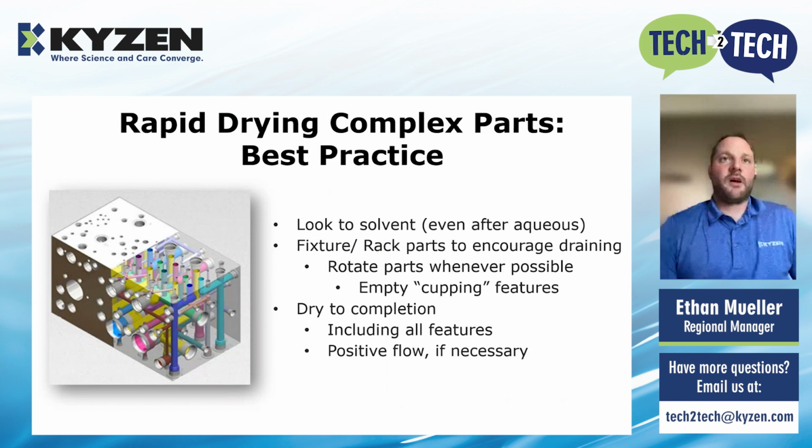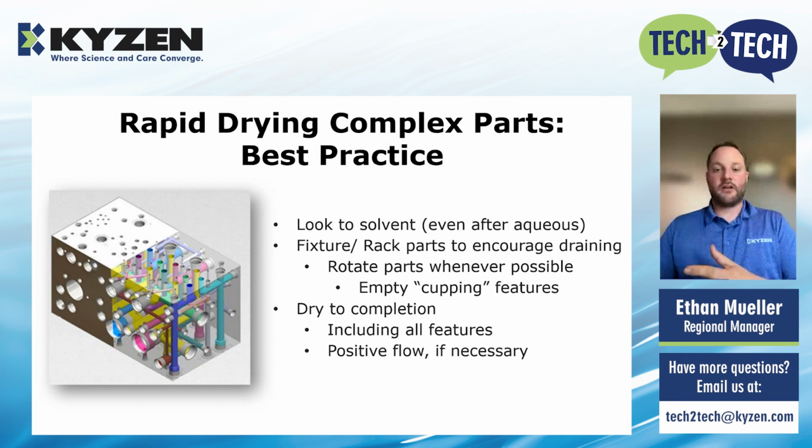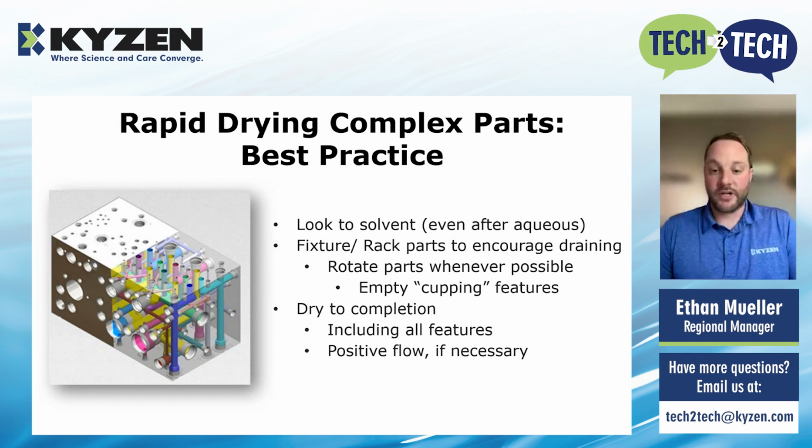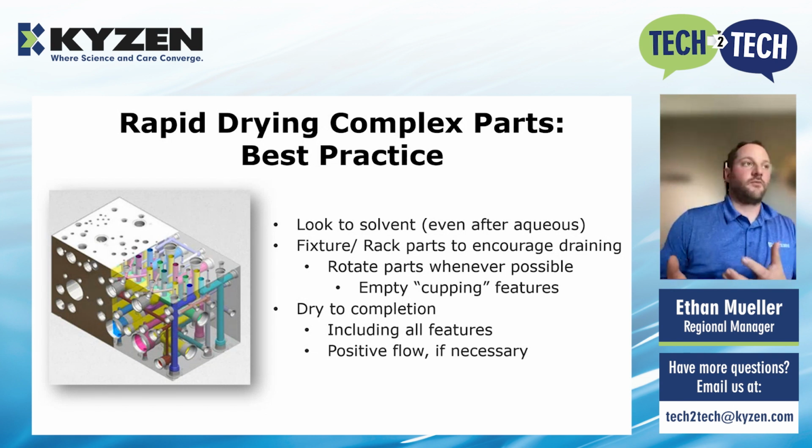So just to wrap everything up here, getting into a best practice, when we have complicated parts that we really need to be able to dry before moving on to the next process, solvent is always going to be a better choice for drying. If you do need to use an aqueous process, you can implement a solvent process downstream as a water displacement method.